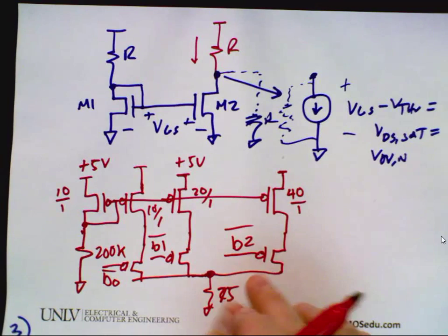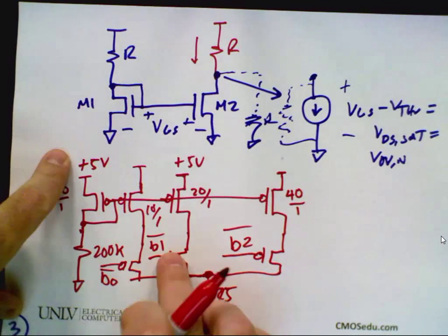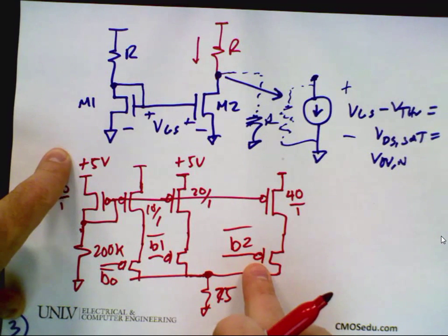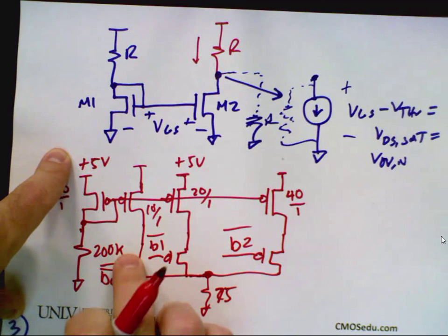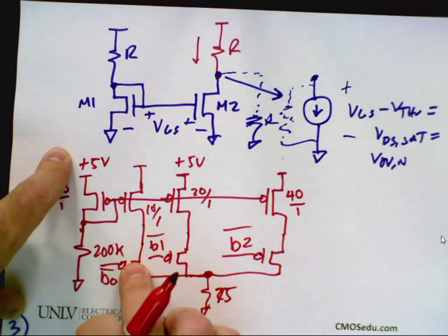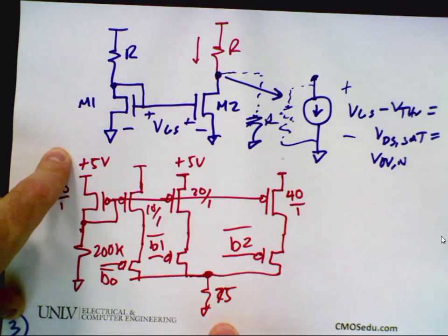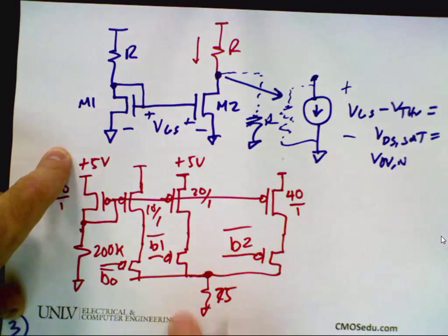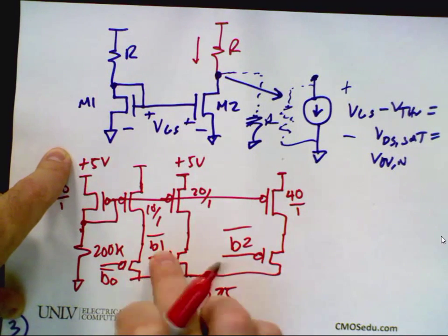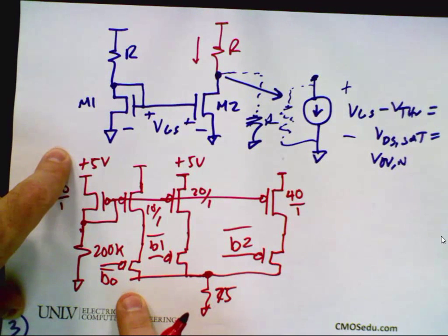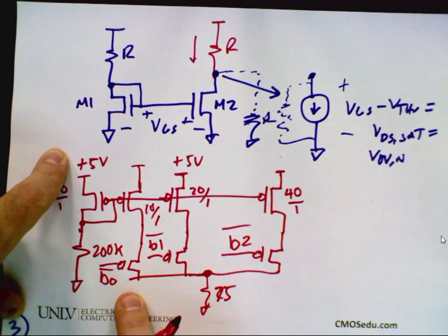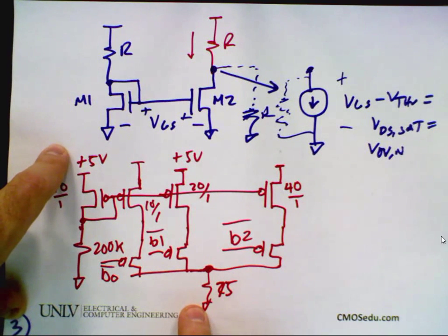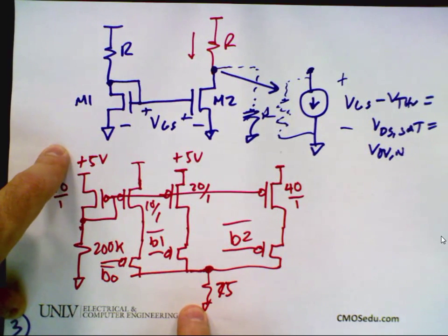So if you haven't taken digital, the way you think of this, when it's a switch, not an analog circuit, is this node, the reason there's the bubble there, is it goes to 0, it turns the switch on. So when it turns the switch on, the current source is connected to the 75 ohms. So if I have 3 zeros, then I have all 3 currents coming down. If I have this as 0 and these 2 aren't, then I just have this current going down. Does everybody see how the circuit works? Very practical digital to analog converter. This is the way it's done.